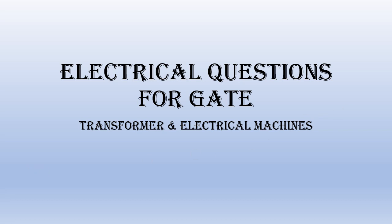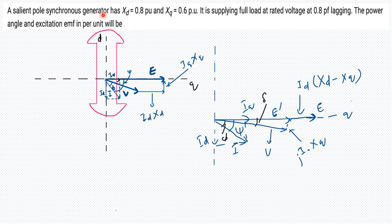Hello friends, today's question is a salient pole synchronous generator with XD equal to 0.8 per unit and XQ equal to 0.6 per unit. It is supplying full load at rated voltage and 0.8 power factor lag. The power angle and excitation EMF we have to calculate for this condition.